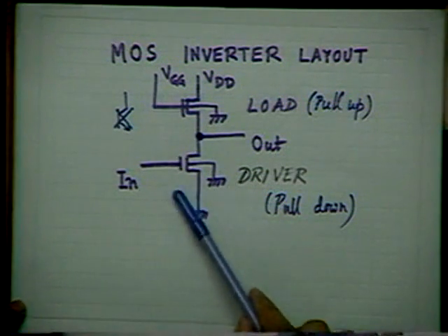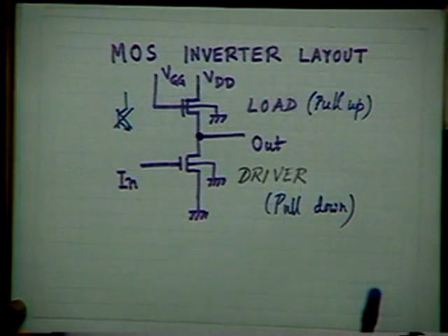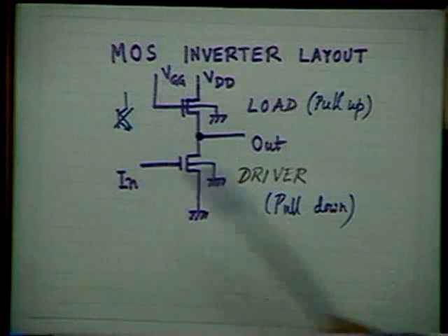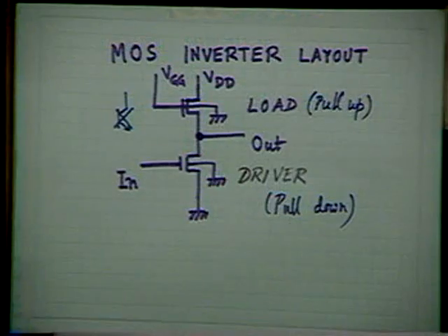However, the driver transistor is always an enhancement mode MOSFET. Why? For input-output compatibility consideration. You understand why? What is meant by that? If the nMOS is enhancement mode, in that case, you know that both the drain bias and gate bias are positive bias. Enhancement mode means it is normally off. Applying a gate bias, you turn on the channel, you turn on the switch.